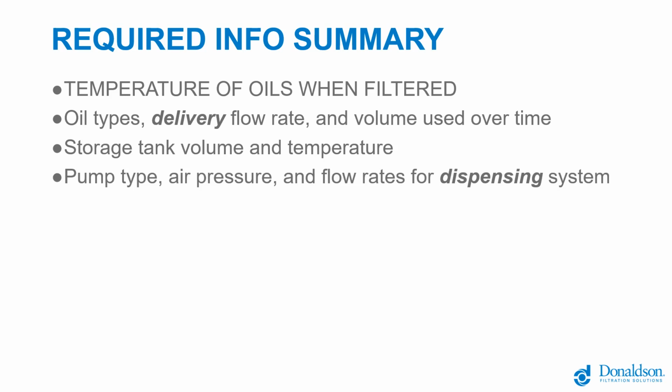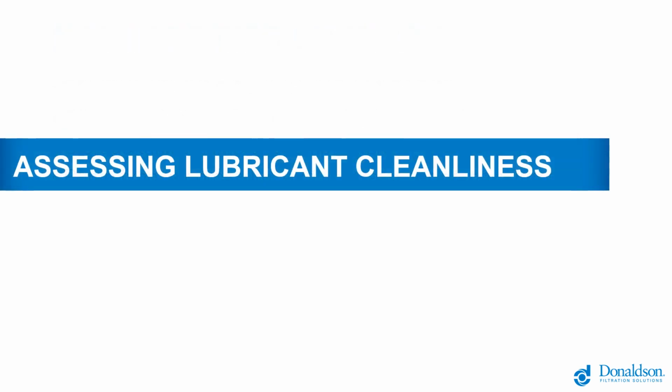So you need to know the ratio of those air pumps on the other side and what kind of air pressure they're running it at. Usually they max out at about 100 to 125 psi for air pressure. And finally, again, a little note about assessing lubricant cleanliness.